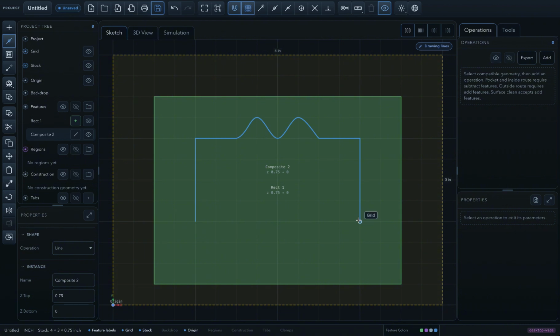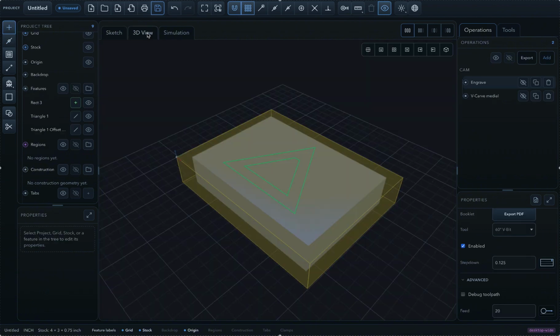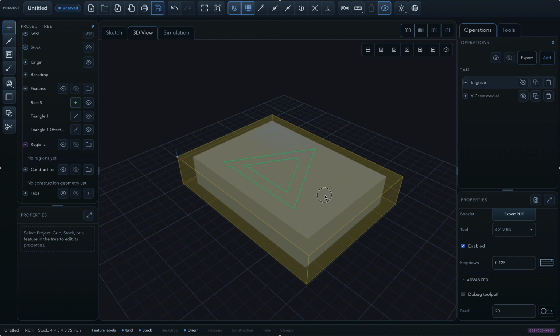This is the right mode for engraving text-like paths, decorative inlays represented by center lines, score marks, layout lines you actually intend to cut, and open geometry that has no enclosed area. For CAM, line mode is most naturally paired with engrave, PureCutCNC's line engraving operation.